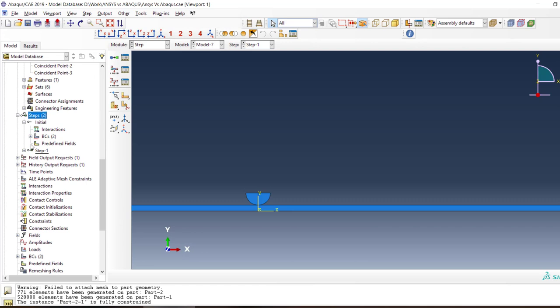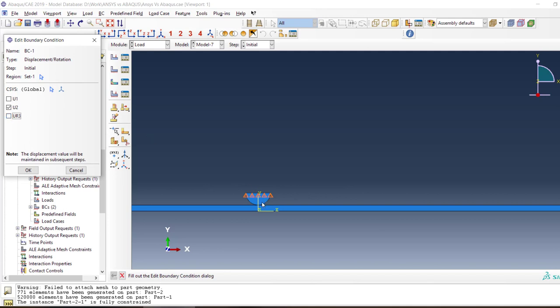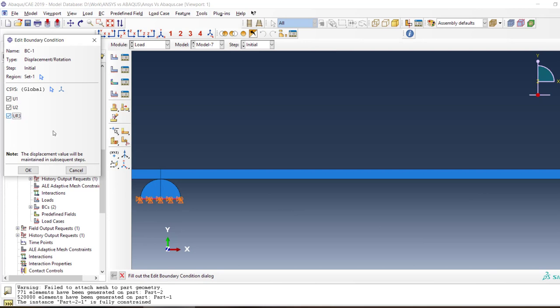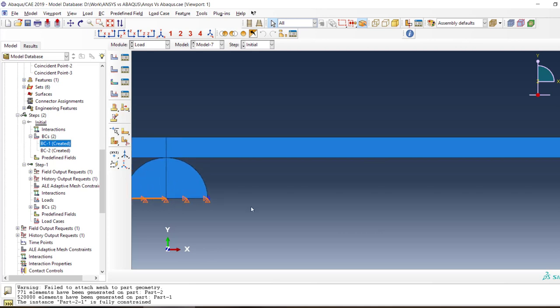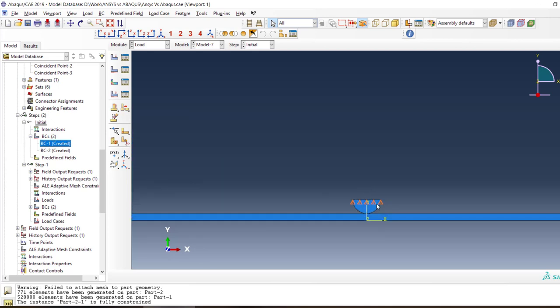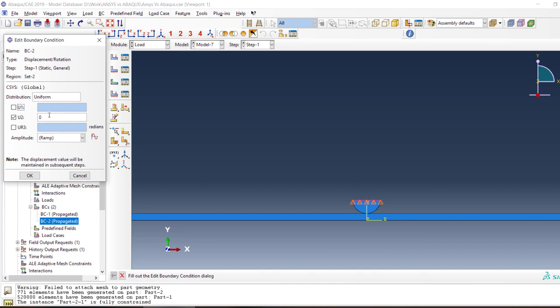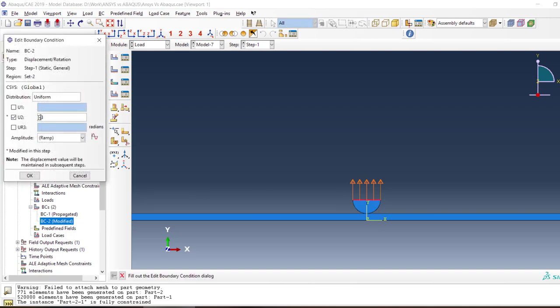So we just hit OK, and one thing we did wrong is that we fixed it all completely. It should only be able to support the Y, these pins. No, it has to be completely fixed, right? Because otherwise it's not the boundary condition. It has to support Y on this one. So this edge is completely fixed, and this edge has the motion of Y. So now we can apply it -3. Oh, oops, -3.